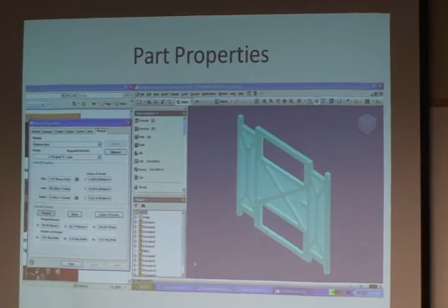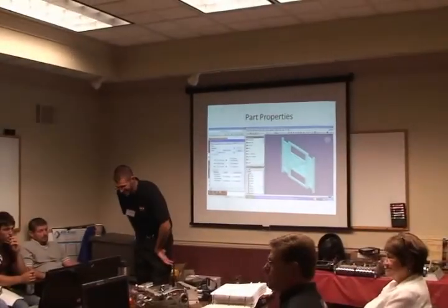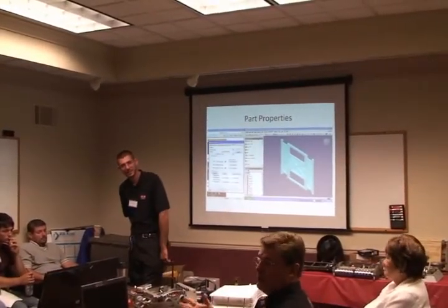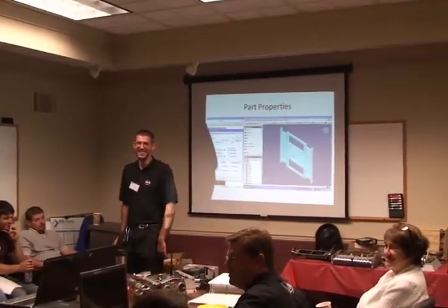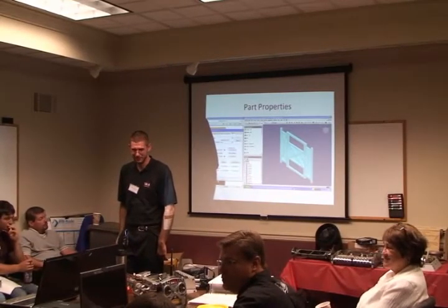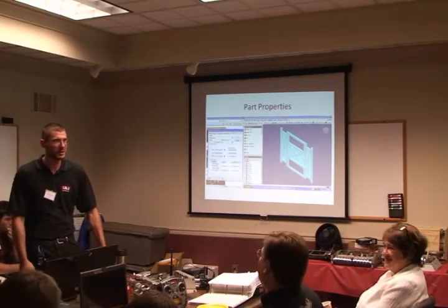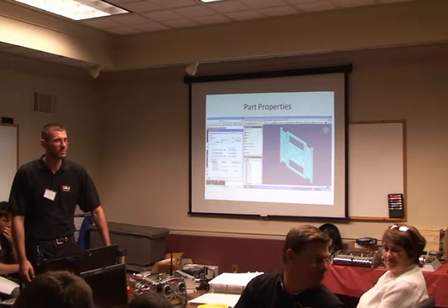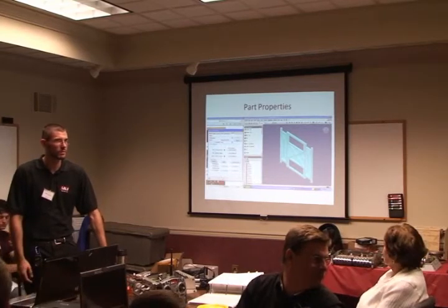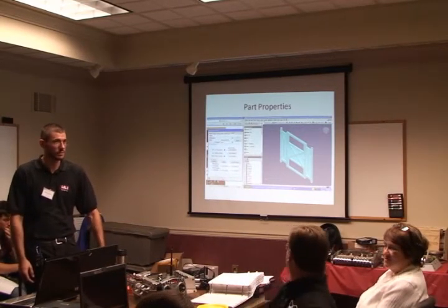One thing that you do have to watch, and this happened to us, is one of my students was designing a weapon and he had the material picked as rubber. It turned out we had this real nice light robot. He liked the color black on his weapon, so he picked rubber. Obviously that's a lot lighter than tool steel. So make sure they have the right properties if you're using these models, that they're not using balsa, or you can actually select air too if you like. If you're using something that you don't know, it won't have the density value for you. We're going to show you a bit later there are tables you can get that show the density value. That's basically the value that you put in there. Just plug it right in there and assign it that value.